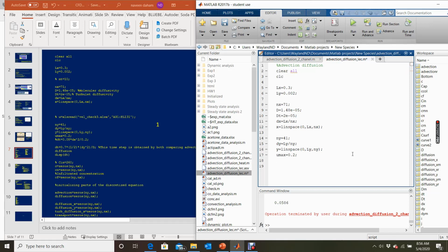Okay, so now this is a very crucial step, defining the time step size. There is a way to get the time step size. I'll encourage you to go and study the CFD methods by Majumdar, which is a very well-known handbook of computational fluid dynamics. In this book it is clearly shown how you can get the accurate time step to converge the solution. Otherwise you may end up with a random time step. The time step has to be in the order of magnitude of the geometry, or the discretized cell size. Okay, so this is a way of getting that.